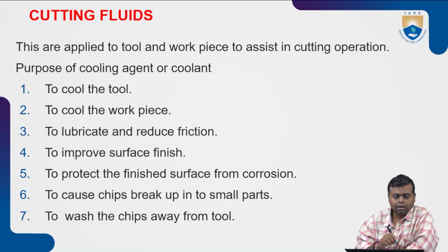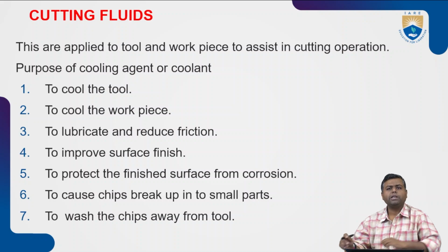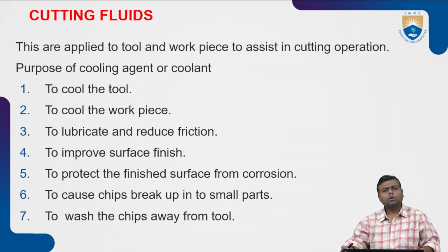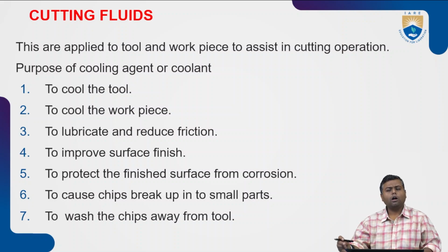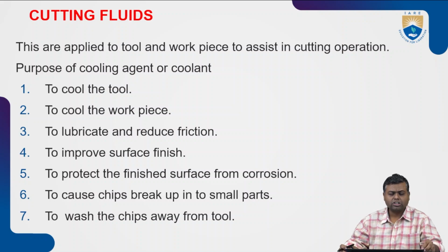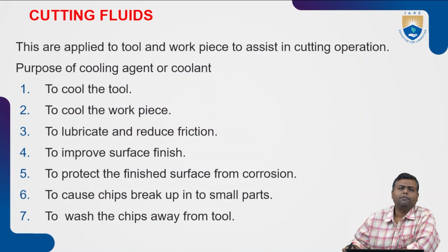In general, the purpose of the coolant agent is to cool the workpiece or the tool, to reduce the friction, to improve the surface finish, to reduce corrosion on the finished product, to break the continuous chips, or to wash away the chips in a flow.